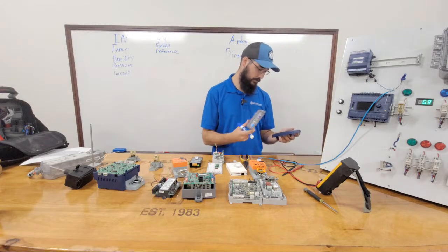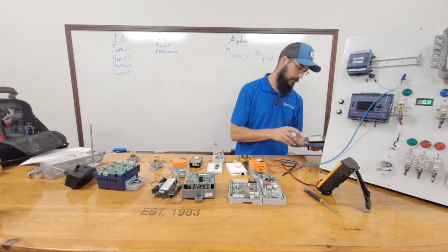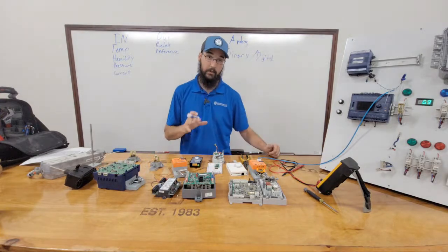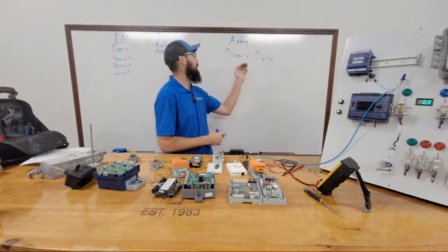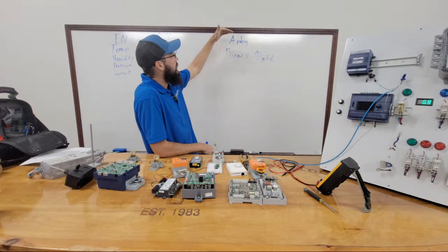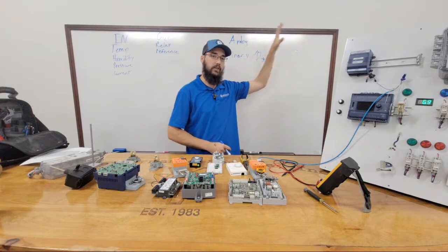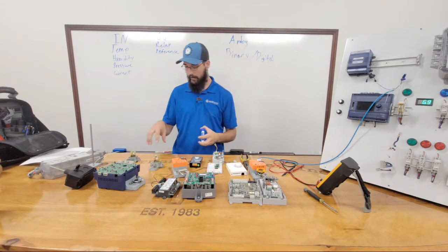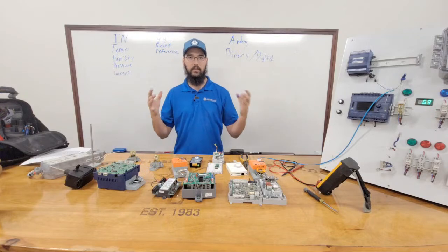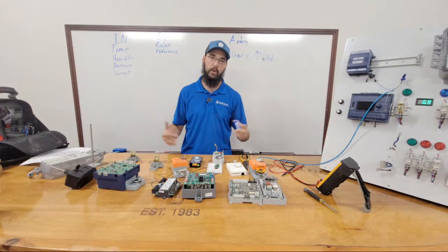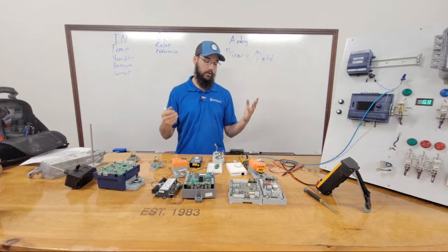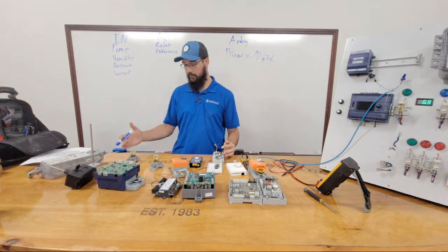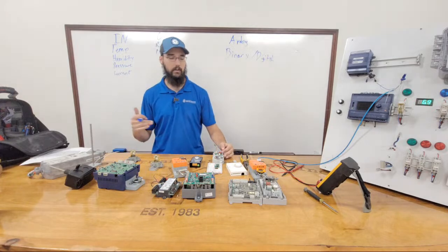Distech says digital. I know that you'll run across some of them. They'll say binary, so just take that for what you will. Point is, these are the same thing. So analog is a varied signal of any kind, meaning that it has a 0 and a 100%, and it can be anywhere in between at any given time. So whether that's 1 volt DC, 2 volt DC, 5 volt DC, 10 volt, whatever.